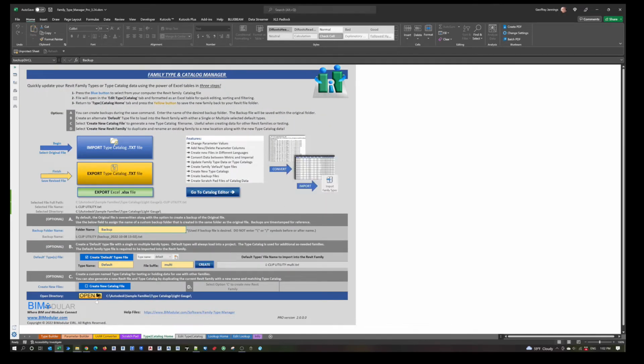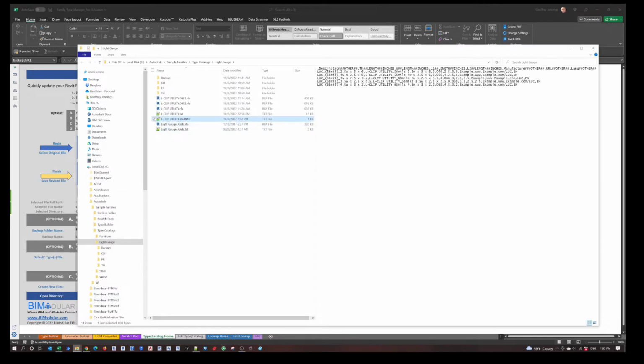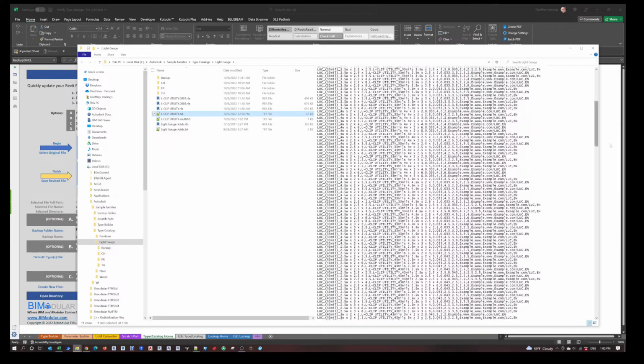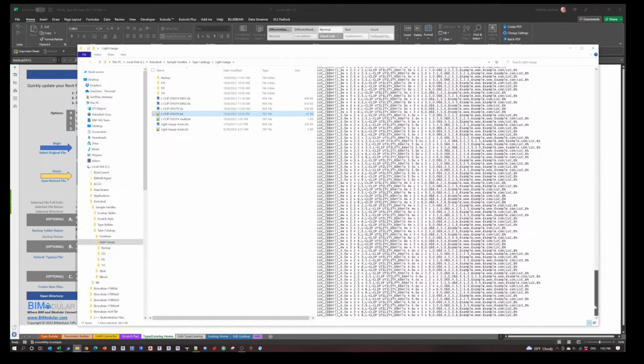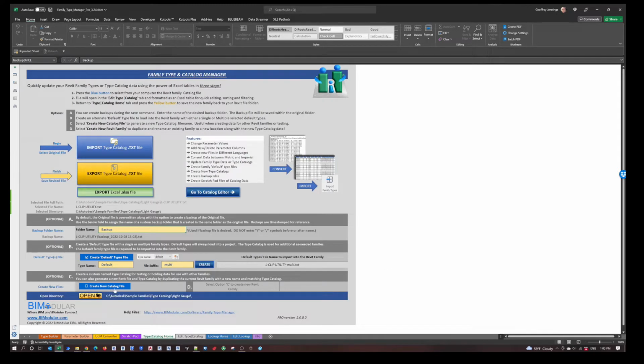That's done. So go in here to look at open. You'll now see we created the multi-catalog, and here are the 5 that we selected. So we can then later on in Revit load these back into the family as our default standards. And here's our master catalog of all 420 options. That completes the process of the default catalogs, and now we're going to go into creating a master catalog with all of the international and changed to metric and imperial settings.